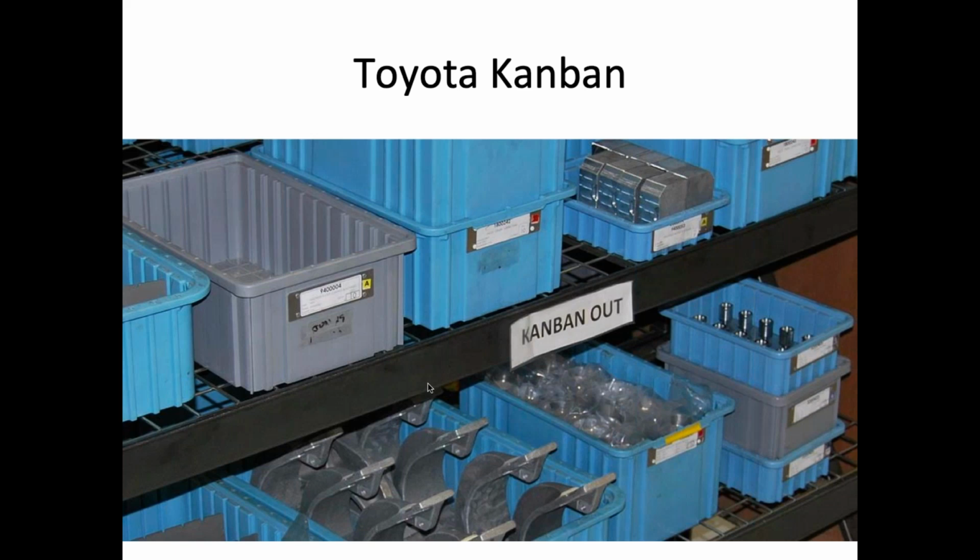And it was really a similar approach to how to control the release of work through the system based on making sure there wasn't too much inventory being built up. And they used the trays to minimize the amount of inventory that can be built. And so you essentially had a small buffer in front of each process, but you couldn't continue to build if there wasn't an empty tray available for you to put it in. And that's how they managed inventory in the system.